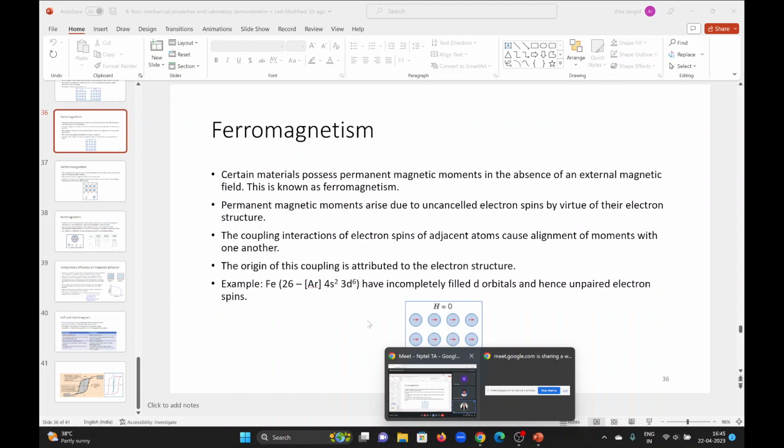And for the 111 plane, it will be 4 upon root 3 a square. So you have only one option that is common, 2 upon a square. So the question must be framed as you have said; it should tell along which plane, because planar density will be different at different planes.